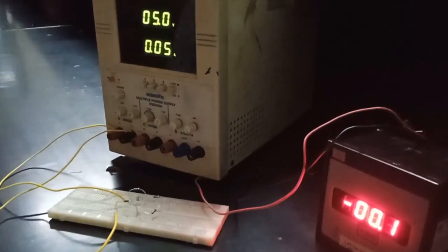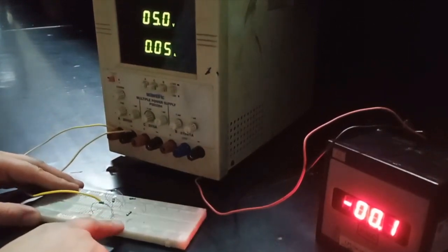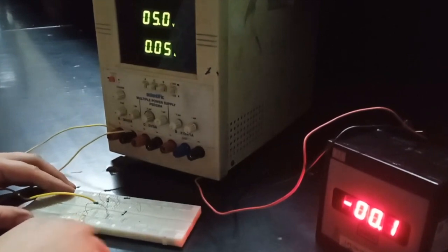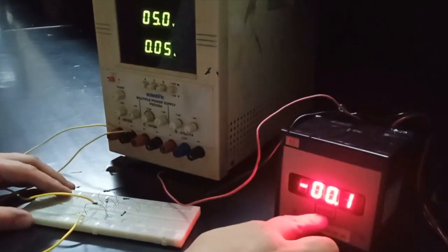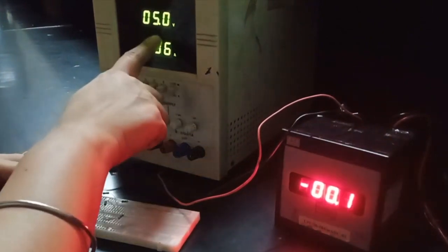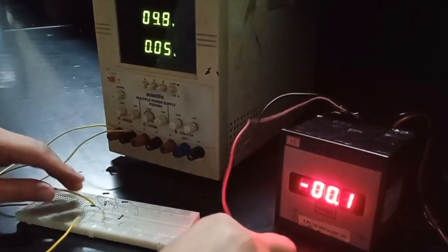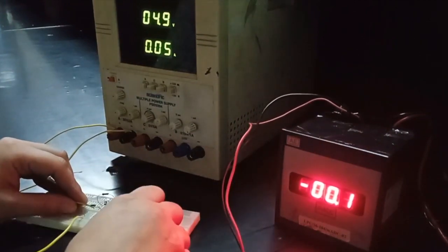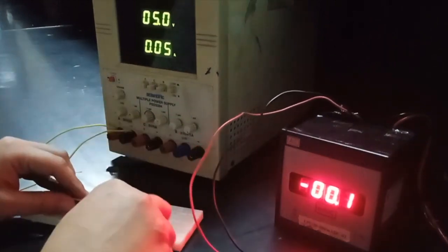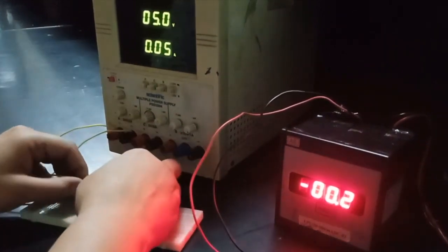Okay, so now I am going to verify Kirchhoff's current law and I have taken the same circuit diagram once again. The same combination of R1, R2, R3, R4 and R5. But now I have taken an ammeter instead of a voltmeter. The input voltage is also set to 5 volt. Let us first of all calculate the current I1 flowing through R1. As you know, an ammeter is always connected in series. Hence we have to break one connection and introduce the ammeter in series like this.